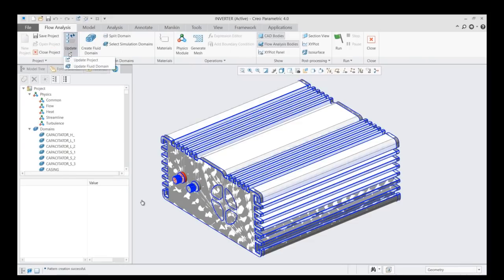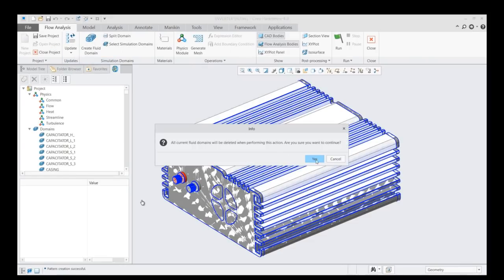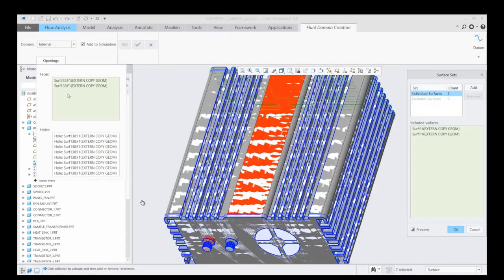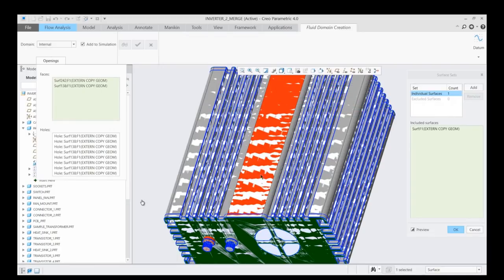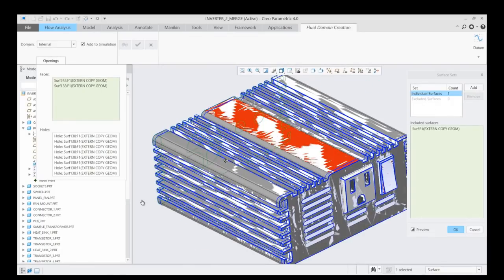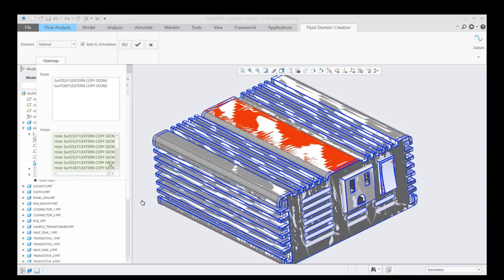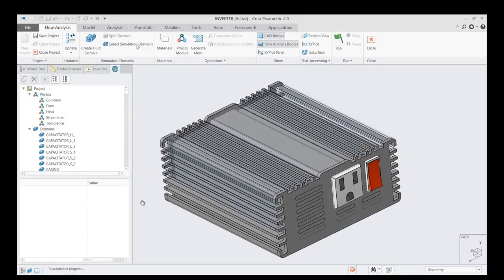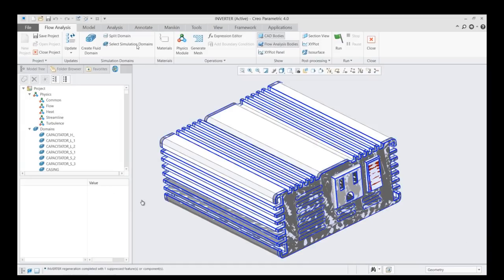And what's really nice about the Creo CFD product is even though we've applied all of these boundary conditions and all of these domains and the different components that are going to take part in the experiment, both the solid and the fluid, we don't have to reconfigure that. We simply have to tell it the extent of the experiment volume, and everything else is carried over from the analysis that we created previously.